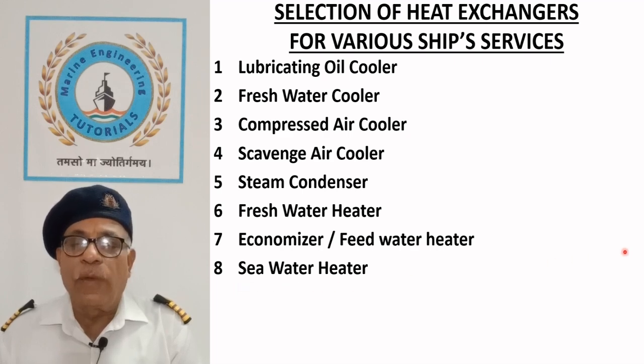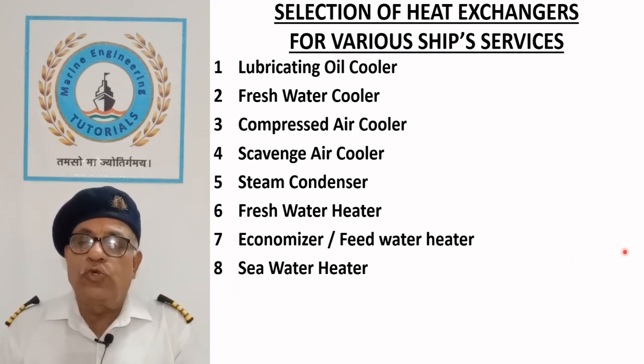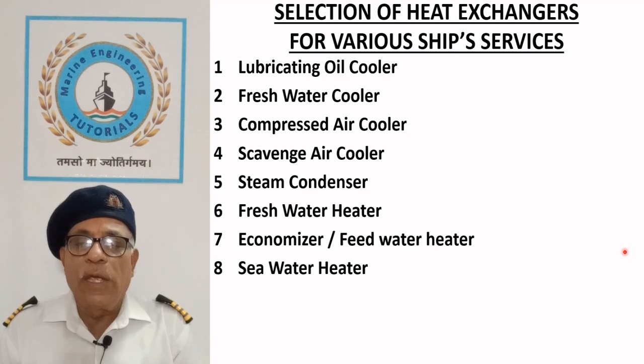Seawater heater. Seawater heaters are used on conventional oil tankers for washing the cargo tanks and lines while preparing them for inspection or repair and during dry docking. Seawater heaters are of shell and tube type where seawater flows through the tubes and the steam passes through the shell.